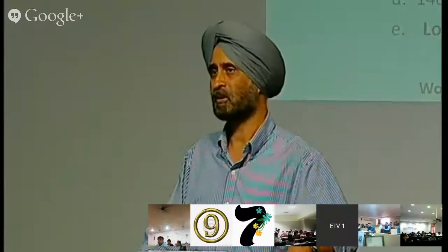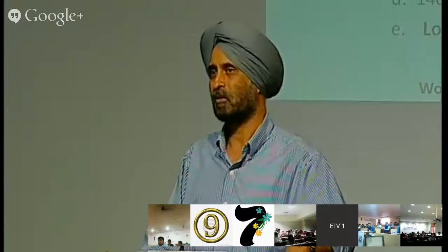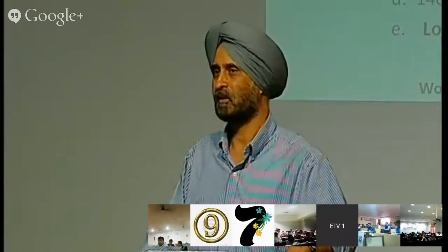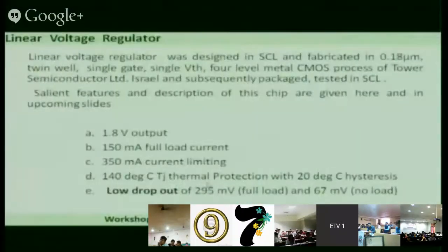There is a thermal protection also, at 140 degree C junction temperature. This means when the temperature of the chip becomes 140 degree centigrade, the voltage regulator shuts down, because beyond this there are chances of burn up.